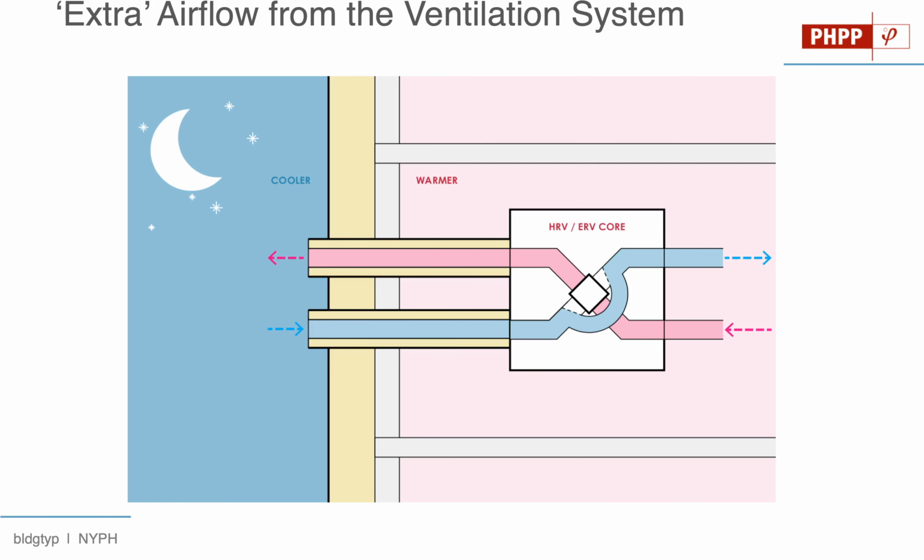And of course, the way the heat recovery system is designed to work is to keep that heat in the building. That's how it's working all winter long, and we like it that way. But in certain times of the summer in particular, that can actually work against summer thermal comfort and energy performance. And so, in those cases, we might want what's known as a summer bypass mode, where we can just take that nice cool outdoor air and dump it right into our building.